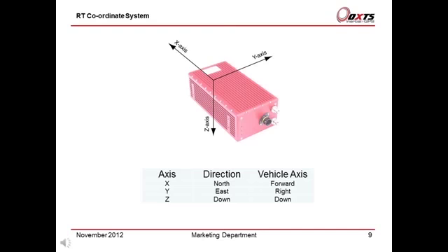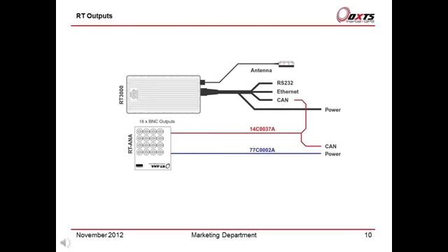Using the RT, it is common to mount the RT with the X-axis pointing forward in the vehicle and the Y-axis pointing left in relation to the car's forward motion. It is important to note the orientation these axes are pointing within the car for use later during the software configuration. Ensure that the correct orientations are applied to the RT outputs if your coordinate system is different.